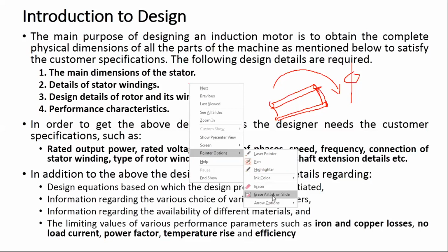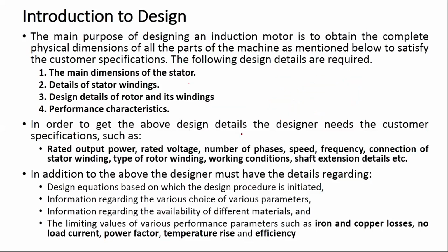Now see, unlike a DC motor, where we purposefully provide current to the rotor and then it rotates, here we have not provided any current to the rotor. It is all because of the rotational nature of the field. You have got some current flowing in the conductor bars of the rotor, and that current is because of the induction principle, right? That is why we call it an induction machine.